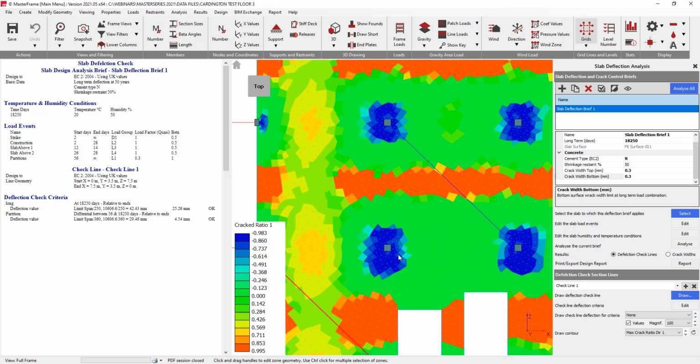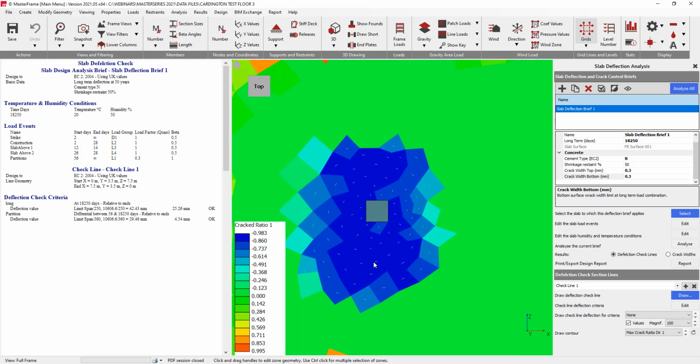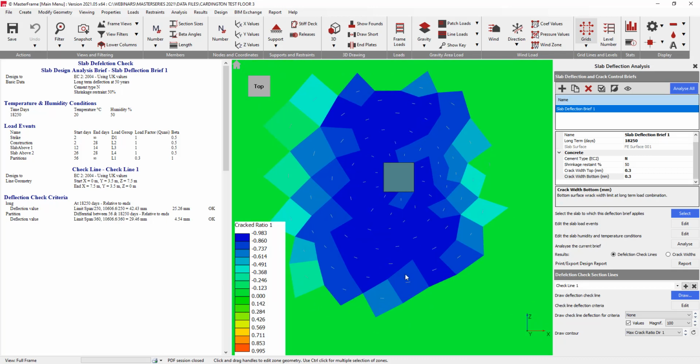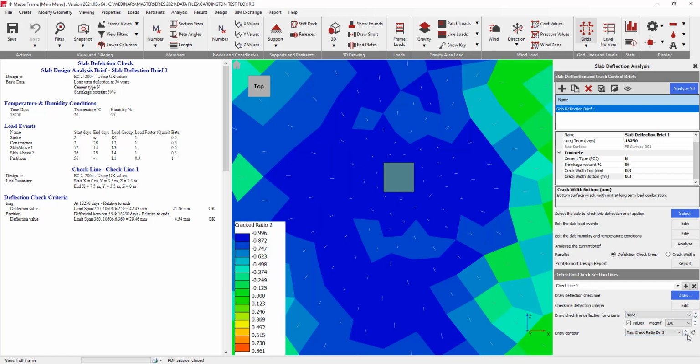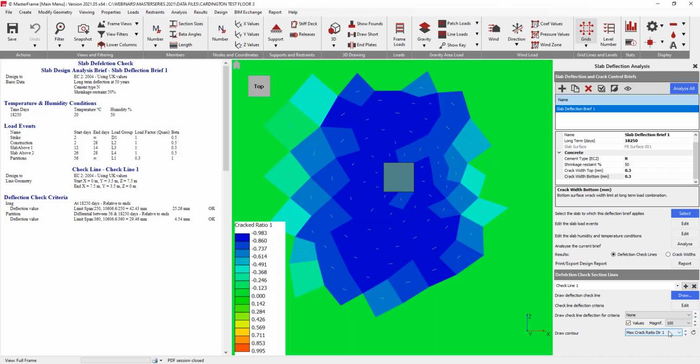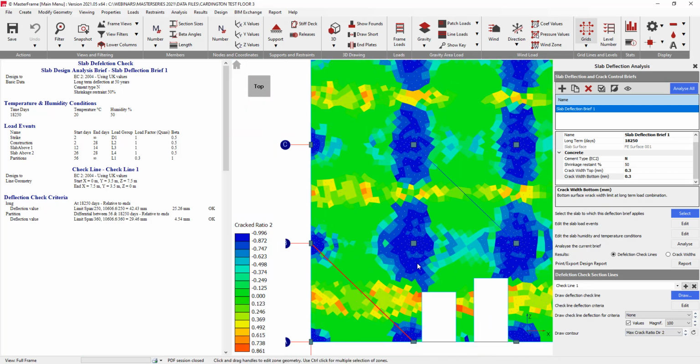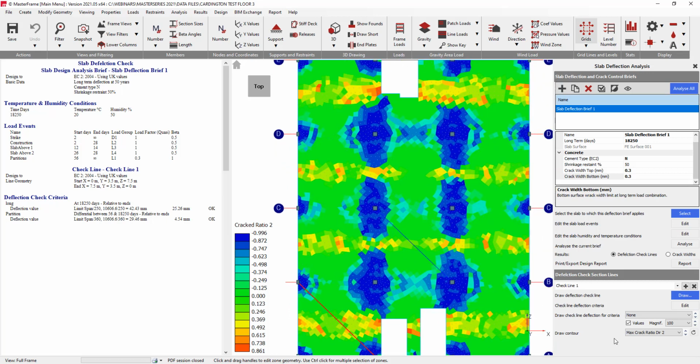So we have here the little grey lines indicating the crack directions, and I'll just zoom in so hopefully you can see that clearly on your side. Cracks obviously occur not just in one direction but 2 directions, and we have the other direction, or the related direction here. Those are resolved into the principal directions of forces, and the cracking itself then is calculated in those 2 perpendicular principal axes, and the directions of those given to you there. So yeah, that's quite interesting just to see the extent of the cracking.